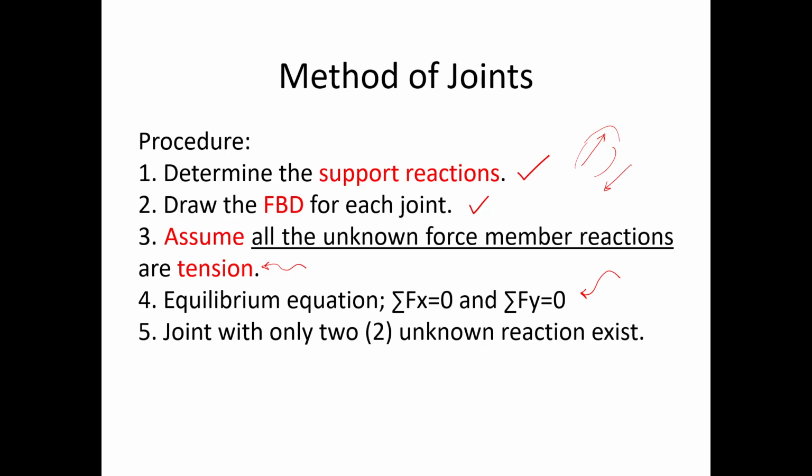All right. So again, as a hint to use the joints, each joint must have at most two unknown forces. If it's less than 2, it's better. But if it's greater than 2, you might have a hard time determining the forces.